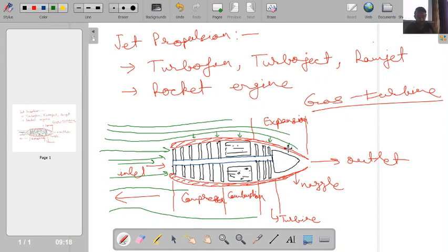So considering the inviscid flow situation, from outside we will have only pressure acting, and particularly this is the pressure of air, because outside we have air only, whereas inside initially it is air, then it becomes high pressure air because of the compression process, and this high pressure air, whenever it participates in combustion, becomes products of combustion. Then it passes over the turbine and the nozzle.